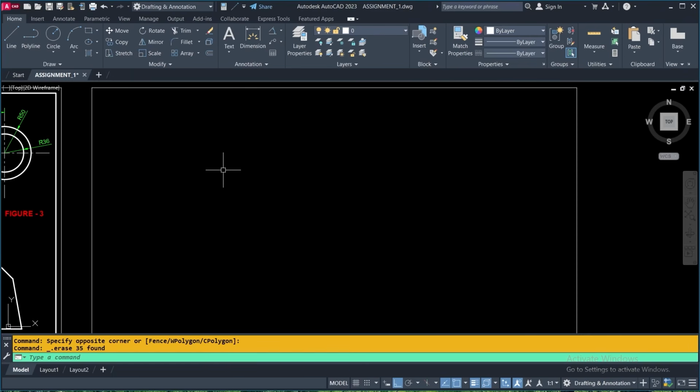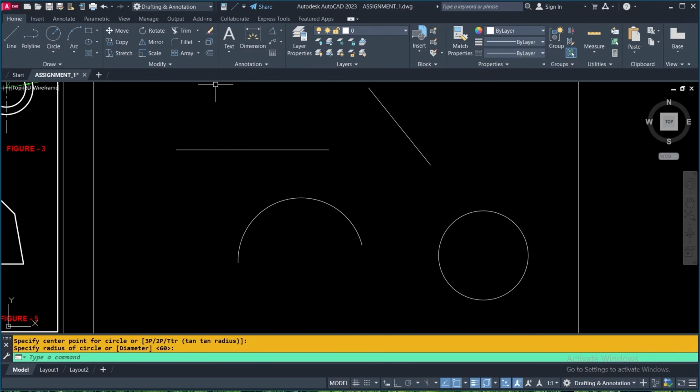Now I am showing you some more activity of the offset tool. Now I am going to the offset tool. Offset tool is here. The offset distance I have to type. I am taking it 10 millimeter, pressing 10 and enter.